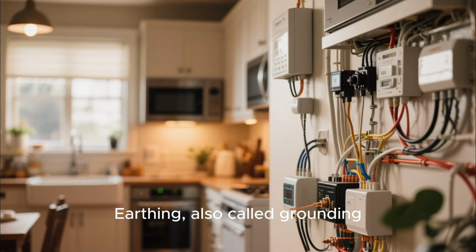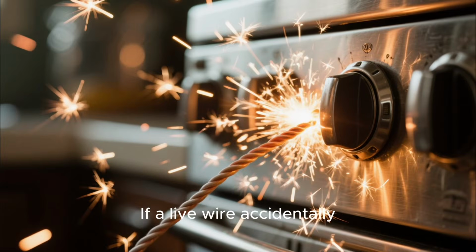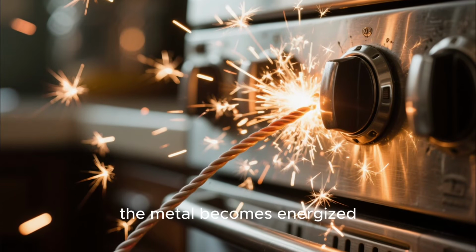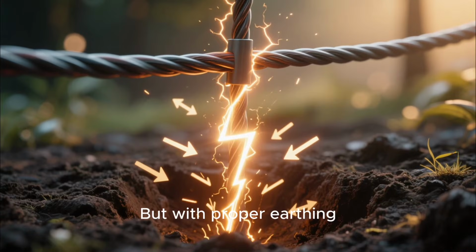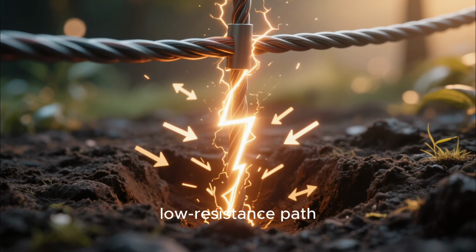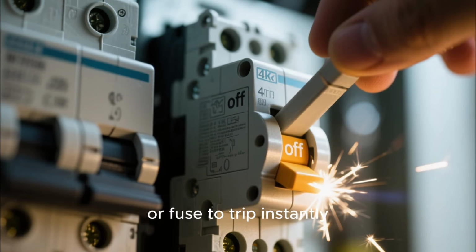Earthing, also called grounding, protects people and equipment from electrical faults. If a live wire accidentally touches a metal body of an appliance, the metal becomes energized. Without earthing, touching that appliance can cause a serious electric shock. But with proper earthing, fault current immediately flows into the ground through a low-resistance path. This causes the circuit breaker or fuse to trip instantly.